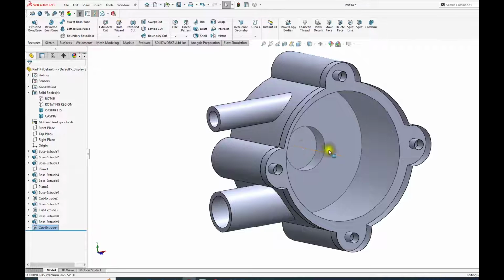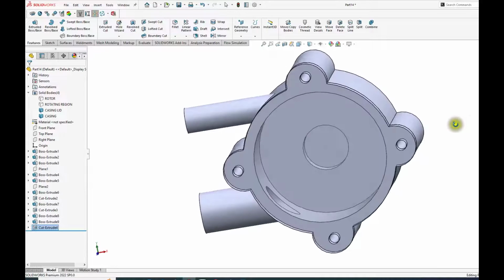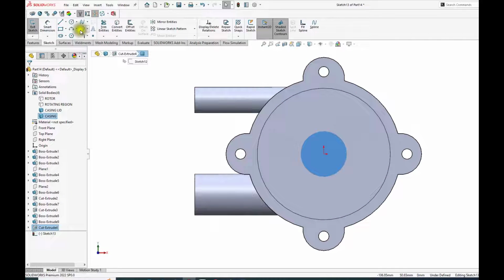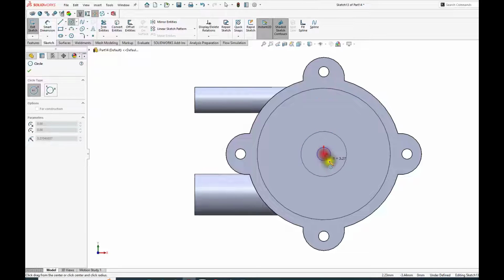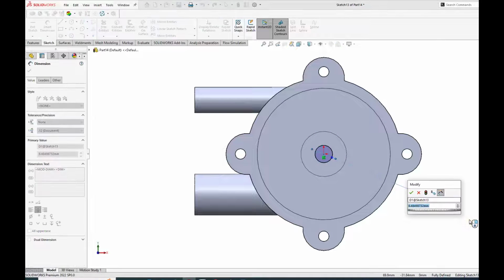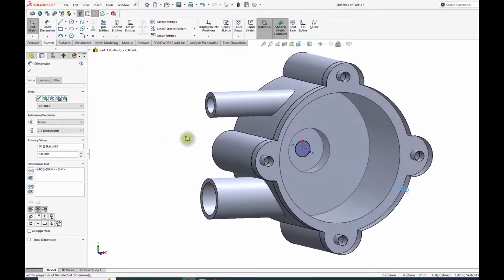Now the shaft through the ball bearing, that's another cut that you have to do right here. So with that said, we go here again, and we do that there, see, and remember the shaft is 8 millimeters, so there's always some percentage that you have to be sure of, that it's not too tight but not too loose either. So I would say 8 at this point, and we're gonna cut that as well.